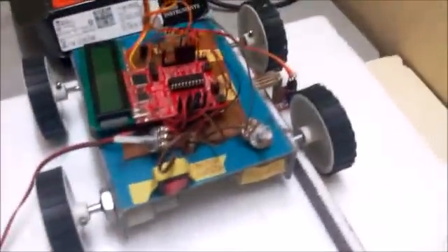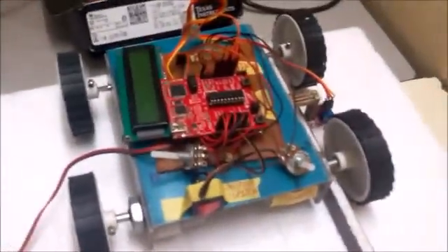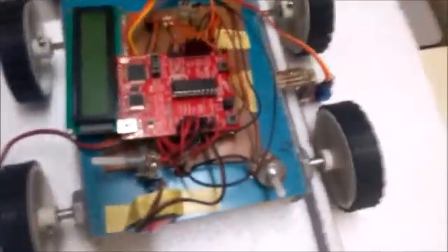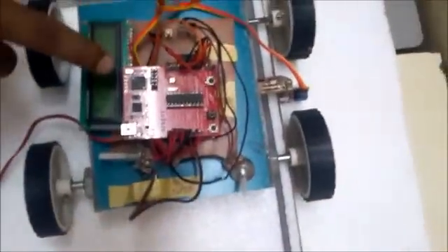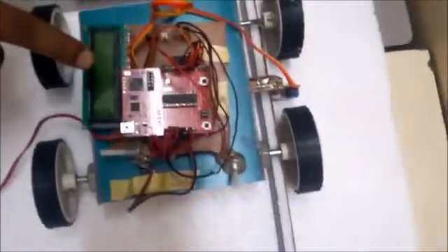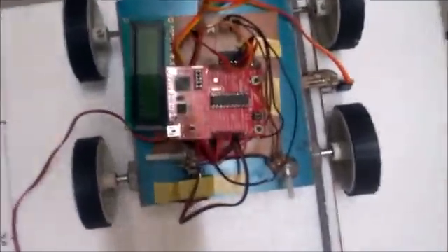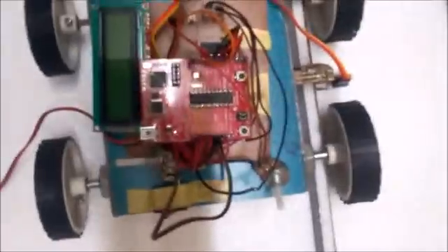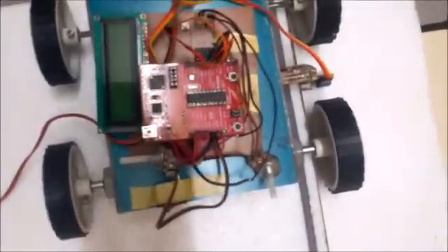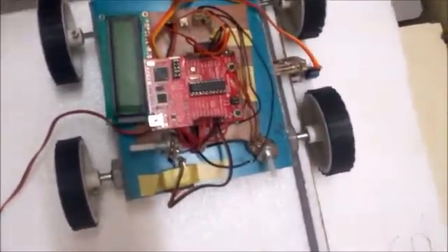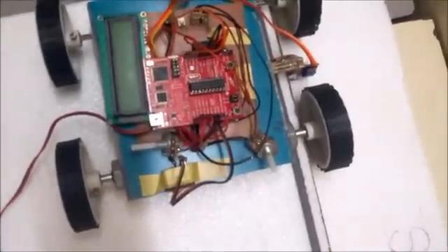The DC motors are operated at 12 volts. They consume 1 ampere of current. Now the next part is the microcontroller of the system, that is the Texas Instruments MSP430 G2. It consumes low power and is easily available in the market. It is mostly used for embedded applications. We can easily interface it with the LCD and other ICs like the motor driver L293D.